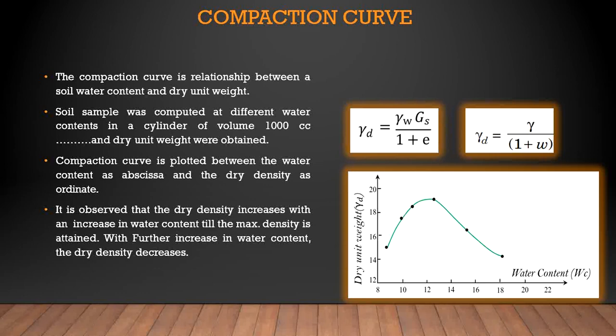And at low water content, the soil is stiff and it is difficult to pack it together. And as the water content is increased, water starts acting as a lubricant. The particles start coming closer due to increased workability, and under a given amount of compactive effort, the soil-water-air mixture starts occupying less volume, therefore effecting a gradual increase in dry density. And as more and more water is added, a stage is reached when the air content of the soil attains a minimum value, therefore making the dry density a maximum.